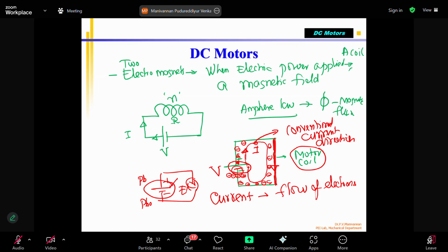Electrolyte is nothing but 80 to 85% water, pure distilled water. It should not have any contamination. And the remaining 10 to 15% is sulfuric acid, correct? Pure sulfuric acid is mixed in, then it becomes diluted. That will be filled inside the battery.